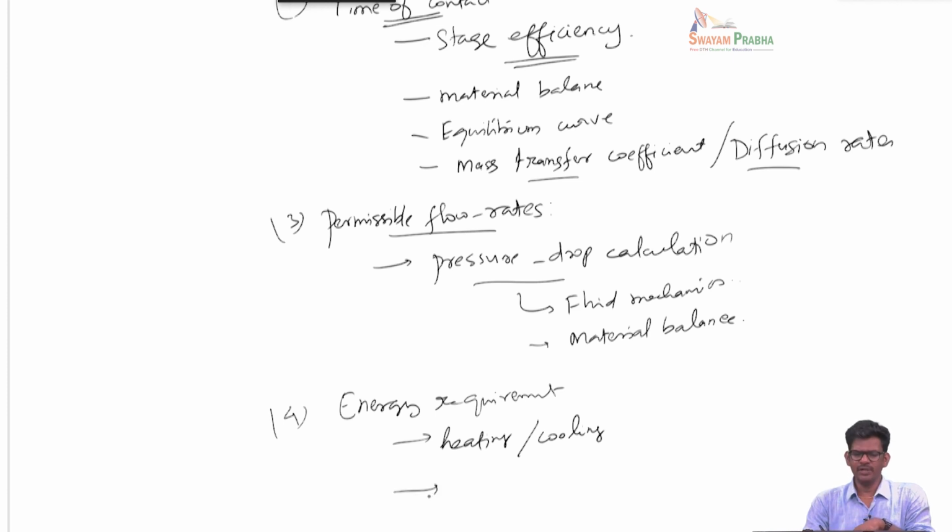The energy is not only involved in this heat addition and heat removal, but also sometimes we use a pump to deliver the liquid or gas, okay. Sometimes we want to dispense the liquid or gas. So pumping cost, fans, any other cost associated with the moving of the fluids, dispensing of the fluids, as well as heating and cooling, all this has to be budgeted out in terms of energy.